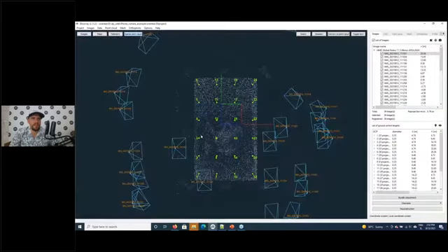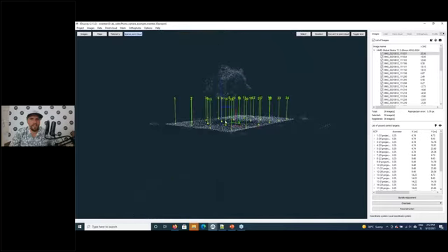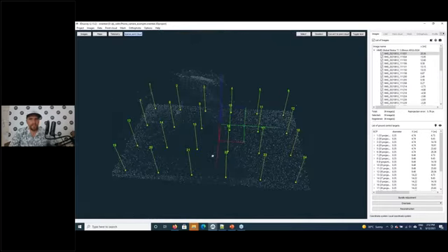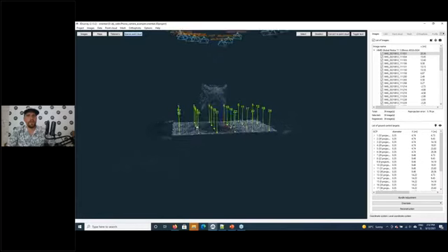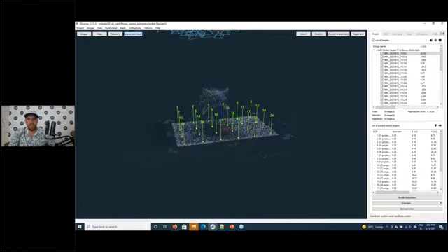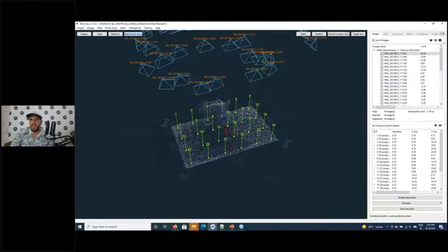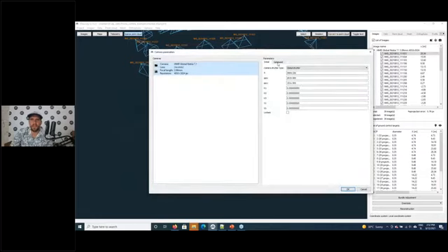Like that. And then we get a sparse point cloud that's calibrated with all these points. Because we did it like that, now these optimized camera parameters should be pretty good ones. So they come in the end to 3200 pixels focal length.